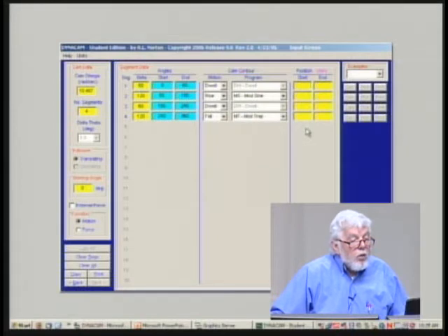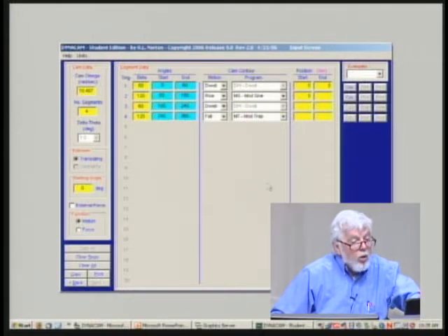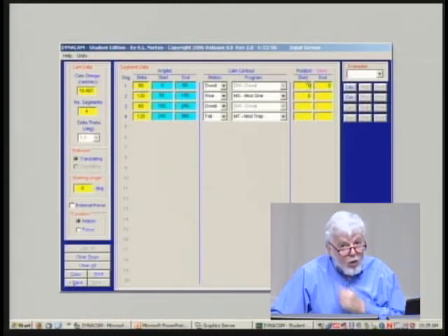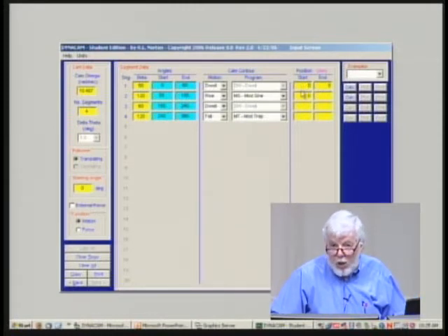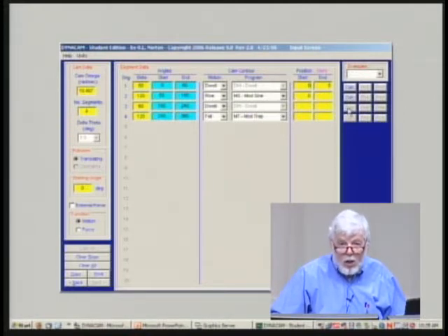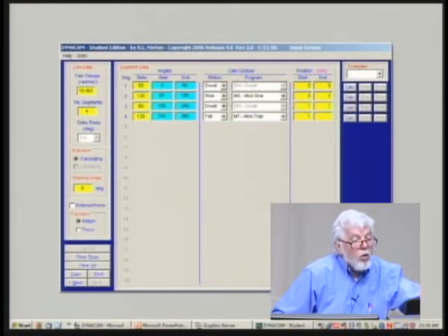Now, the next thing to do is to tell it what the excursion is, what the motion is. And we said we were going to dwell at the low dwell initially for the first 60 degrees, so that's at 0. And note that in the S diagram, regardless of how big your cam may end up being, I'm always starting the displacement at 0 and moving to some larger value, or conversely starting at some value and coming down to 0. The point being that I'm going to go either from or to 0 or possibly through 0 with my S numbers. Now for the rise, we said we wanted a 1-inch total rise, so we're going to go to 1 there, and it fills forward as far as it can.